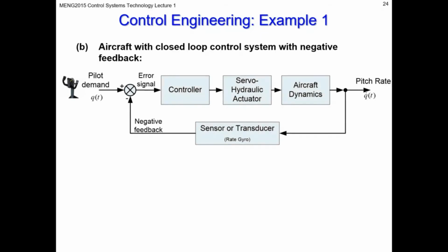So, yep, that's correct, Adidova. The feedback fixes the problem that the system experiences. That's the point of the feedback. It's able to look at this difference, and the algorithm in the controller is supposed to close the gap between the current demand or the set point and the feedback as fast as it can, safely. Right, so it has to drive this feedback error towards 0.